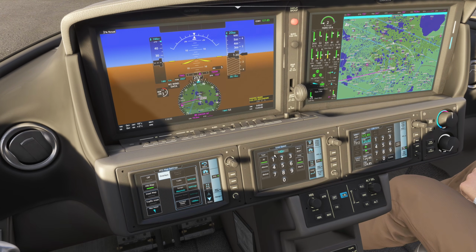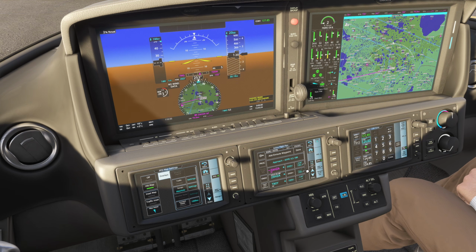So I want to make sure the plane automatically changes it to 140 knots, then we click enter and it's programmed in. I want to do the same again here. We don't have to do it, I'm just trying to make it easier for us. So we want to be over the runway threshold at 90 knots, right? So off the fence of the runway, we want to be that slow.